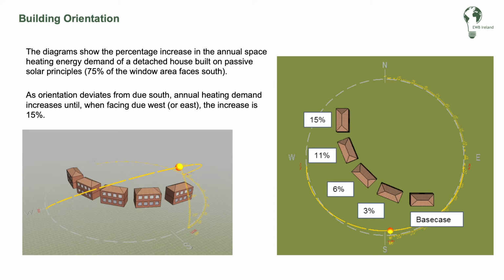So to go through some of those principles in a modern context, this is a very simple model of one building just rotated a few degrees from south. Everything about it set up in this model is exactly the same: insulation levels, air tightness, the size of glass, literally everything, floor area. But if you rotate that from south to west, there's a 15% difference in heating on it. And that is, as I mentioned earlier on, we had the easterly sun this morning heating this place up.